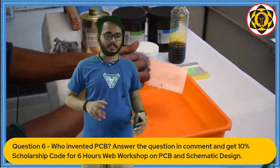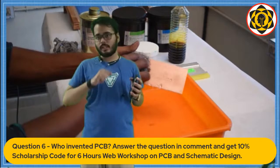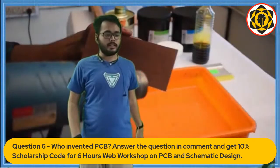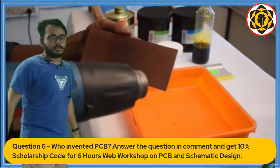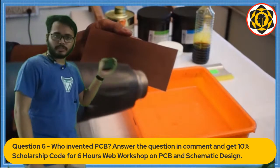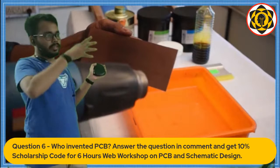So my advice is just wash it with soap water. Nothing fancy. Just wash it with soap water, and then dry it with a blow dryer. This is a very important step, because if you dry it under the sun, it will rust, because there is air and there is moisture.